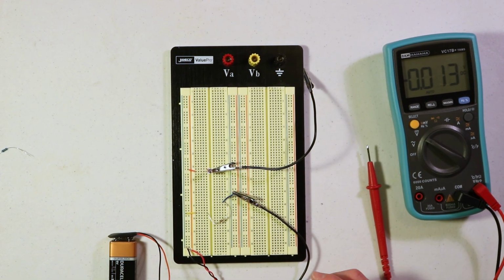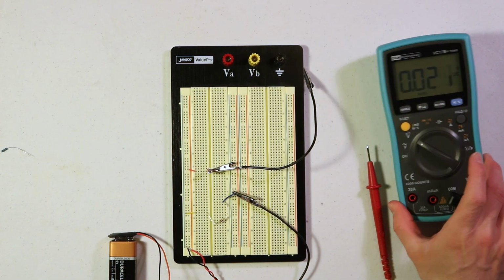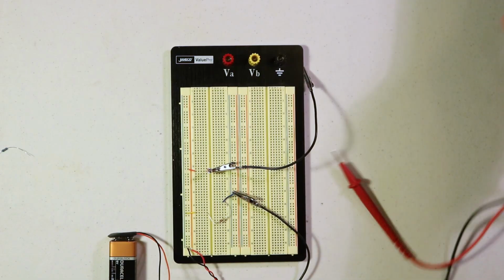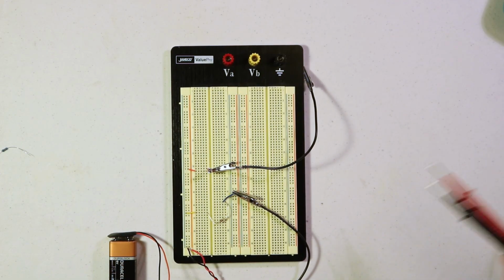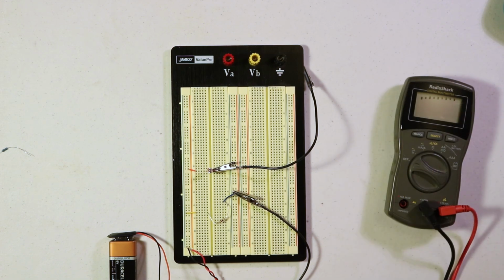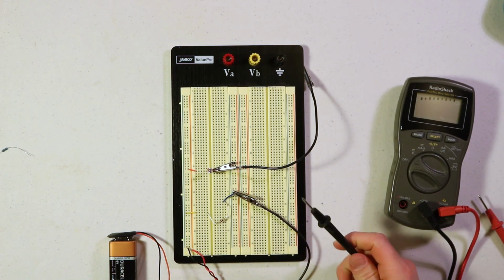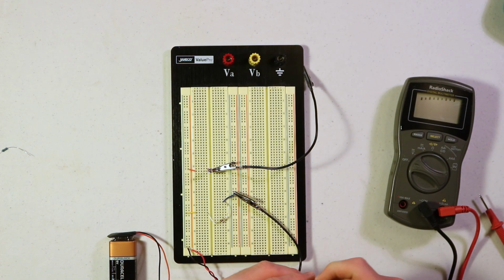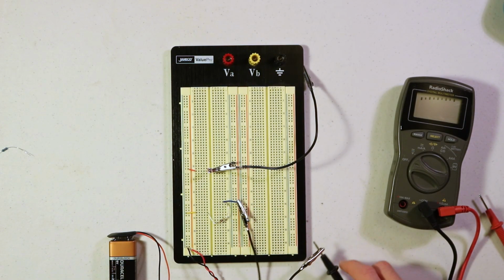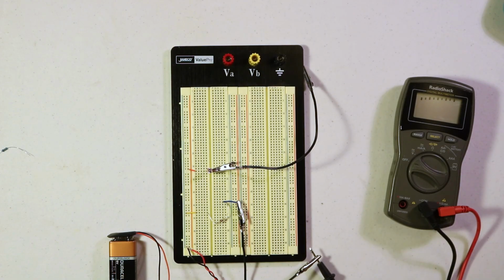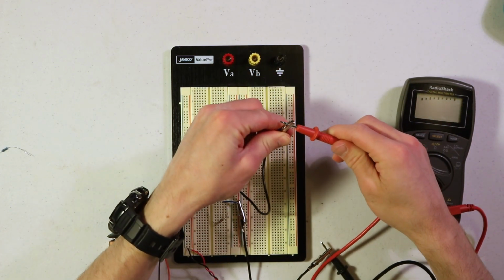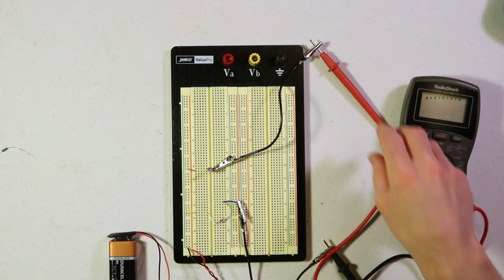Now unfortunately, as I mentioned earlier, I can't measure current with this one anymore, at least the low amounts of current. So I'm going to have to set that one to the side and grab my other multimeter for this part. So we'll just take the negative lead from our multimeter and connect that one to this wire coming in from the resistor, and then connect the red one, the positive lead, to the other alligator wire, and we'll just set that to the side there.